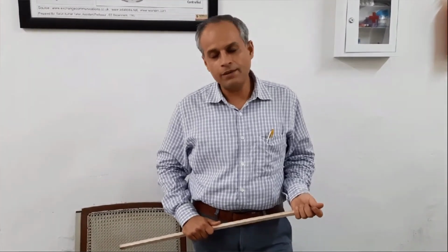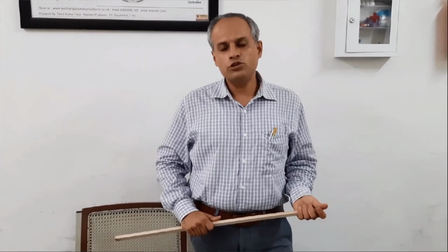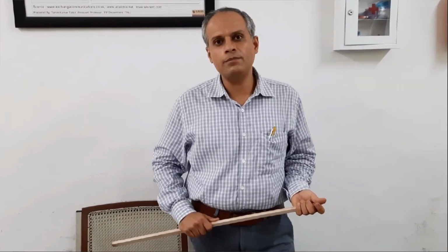At the same time, the control circuits, what we are going to see in case of experiment 9, the star delta starter and the DOL starter, in our laboratory we have a setup for them. So we will also show you the operation of direct online starter and star delta starter from the contactor point of view. Here we are not going to put any real motor, but this is just the control logic understanding for this contactor based motor panel.